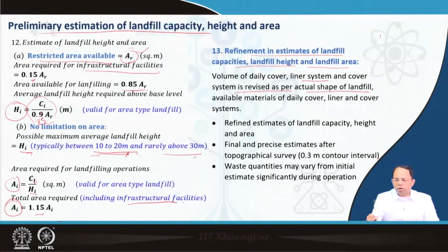Because if I go with a landfill which is like this, it will require a certain kind of cover. If I go with a landfill like this, it will require another volume of cover. Even though the overall volume remains the same, this has to be re-estimated as per the actual shape of the landfill, and also depends on available materials for cover, liners, available soil that would be used for making these liners and covers. So we have to refine the estimates for landfill capacity, height and area.